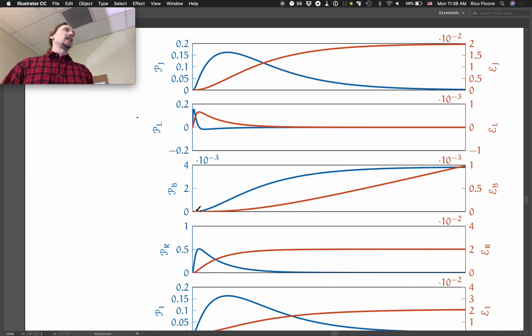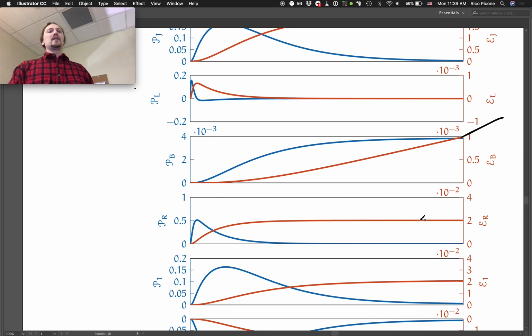So at first you're not dissipating anything when you're not moving. But as you start moving, the damper is going to dissipate power. At a certain velocity, it's going to dissipate a constant amount of power, which still accumulates though, right? So at first this energy that it has dissipated was increasing rather rapidly, but then it starts to level out and becomes linear. So after this, it continues to rise, the orange line, but it's linear. So you're always losing power. I guess it would be better to say, you're always losing energy from your system into heat from the damper whenever you're going at a non-zero velocity.